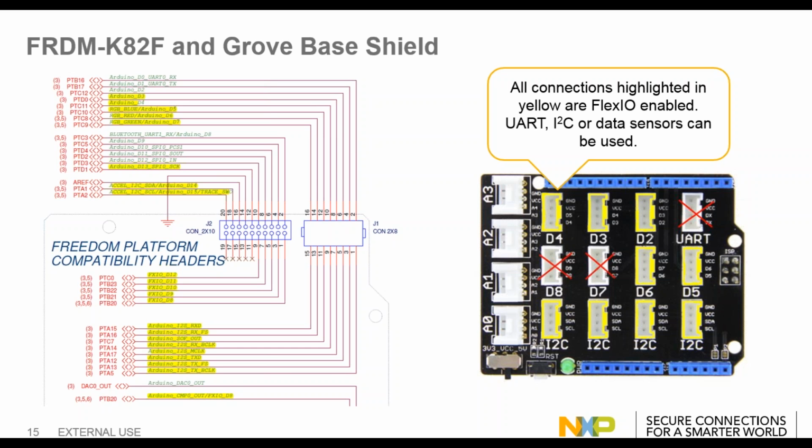But besides the I2C, you have the connections for D4, D3, D2, D6, and D5. And one great thing about the Grove sensors is their pinout. Their pinout is standard, and so you can see, if you look closely on the board, it simply has a ground, a VCC or the power, and 2 pins.